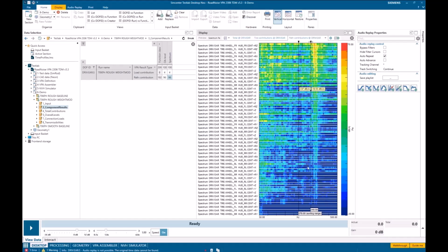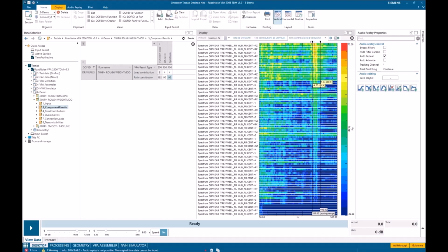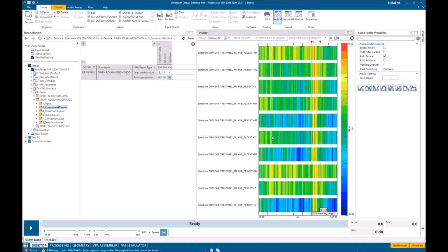And if I make this a little bit more narrow, move it over to this 380 region, I don't need to look at all of these guys down here, right? I really just want to know what are maybe the top 10 hitters. So I'll say view, show me the top 10. And as it's no surprise, these are front left, front right, front left, front right, right? There's no rear tires here in the top 10.